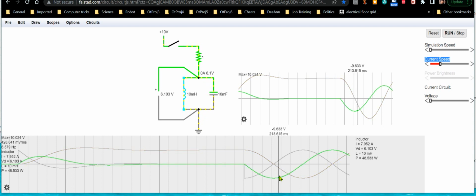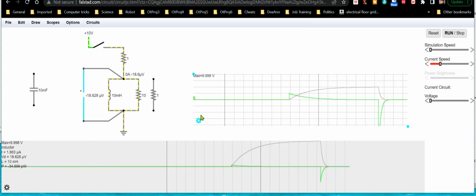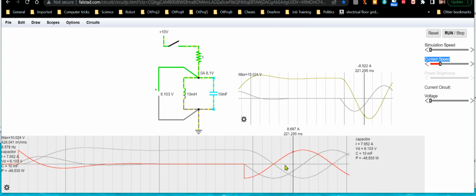The capacitor wants to discharge, so it's actually impressing a voltage across it, just like it did when this was first charging up, as I showed you earlier. The inductor immediately starts generating a voltage across it slightly less than the capacitor, so the capacitor can discharge. But because the inductor is resisting it, that controls the rate of the discharge. So this voltage across the capacitor is slowly draining off now as it charges the current into the inductor, because the current's going negative now, so it's charging up the opposite way.